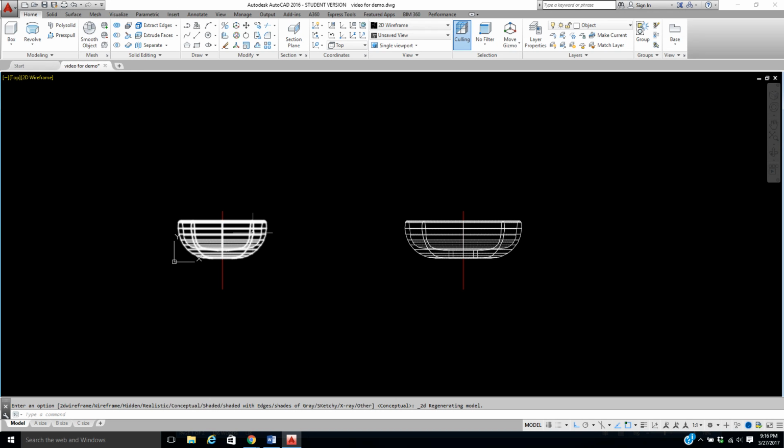So hopefully you liked Revolve. And remember, you don't have to do 360. You can do 180. You can type in whatever angle you want. You don't have to do the full circle. Look at your drawing, see where you're going to save time, and go from there. All right? Hope you like that one.